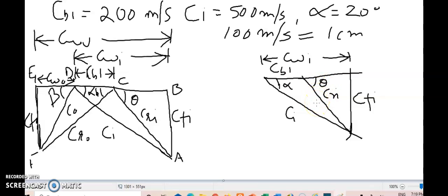So now in the question it will be given that if the blades may be equiangular, or like in one of the questions it was given that phi is 3 degree less than theta. So any relation will be given, and by using that relation let us take them as equiangular. So I have already identified theta, so I can draw phi here at an angle which is equal to theta if the blades are equiangular, and this line is drawn randomly at the phi angle. The length of the line is random, so this is phi.